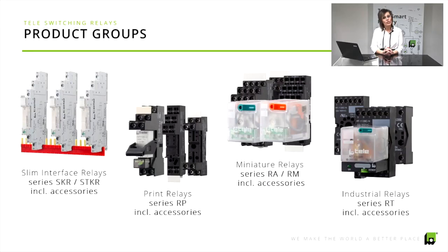Yet, switching relays offer another advantage, and that is, should there be a defect, you don't have to dismantle the complete device, but you just need to take out the relay and plug a new one in. But attention, the system must be in a switched-off state, because otherwise there is danger to life.